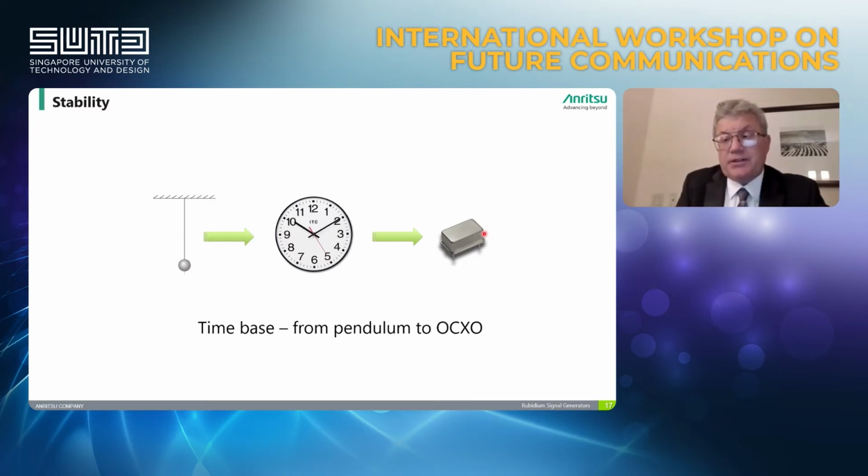This effect is called aging. So although a crystal oscillator is generally very stable, there are still some secondary effects which require recalibrating the output frequency from time to time.